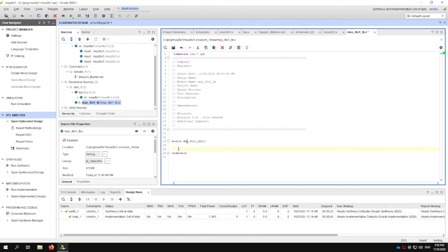So I'm going to explain my approach to simulation. In my approach, what I want to have happen is that every, let's say, 500 nanoseconds, I want to change the values of my inputs and observe the outputs. In order to do that, my inputs have to retain the same values for 500 nanoseconds.